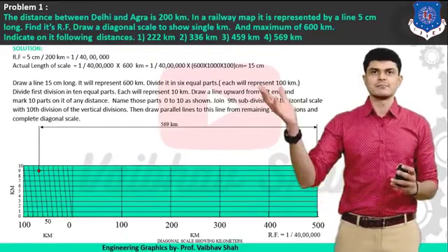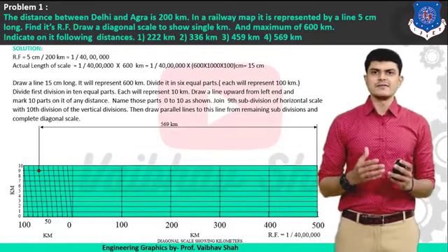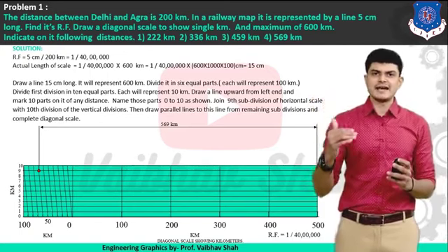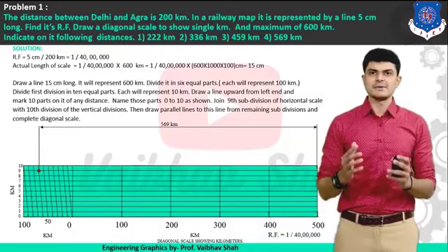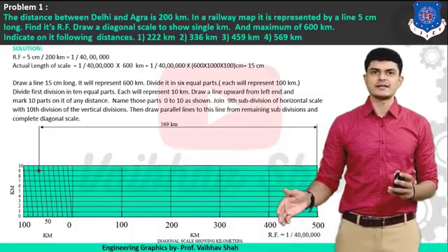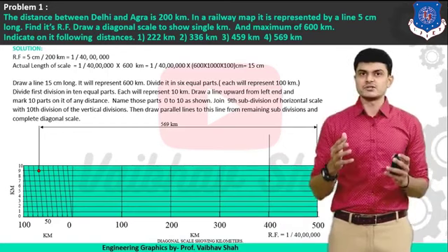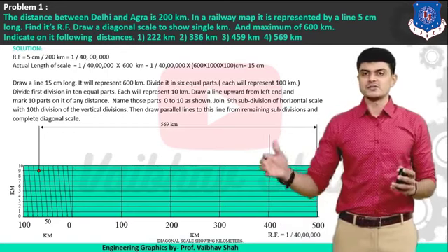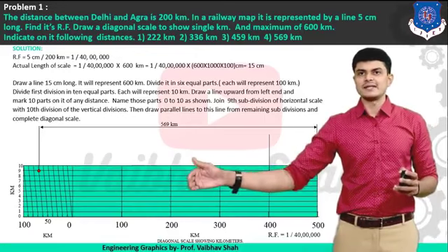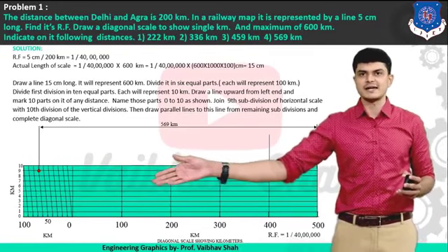We will be taking a third number first, which is 459. So let us start dividing this number into 3 numbers first: 400, 50 and 9. For 400 we are using the primary scale. So let us start 0, 100, 200, 300 and 400. Let us draw one vertical line from 400 like this, as I have drawn. After that, we need to find out 59. That means we need to find out 50 on the secondary scale. So 0, 10, 20, 30, 40 and 50. As you can see on the secondary scale, 50 is indicated there already.